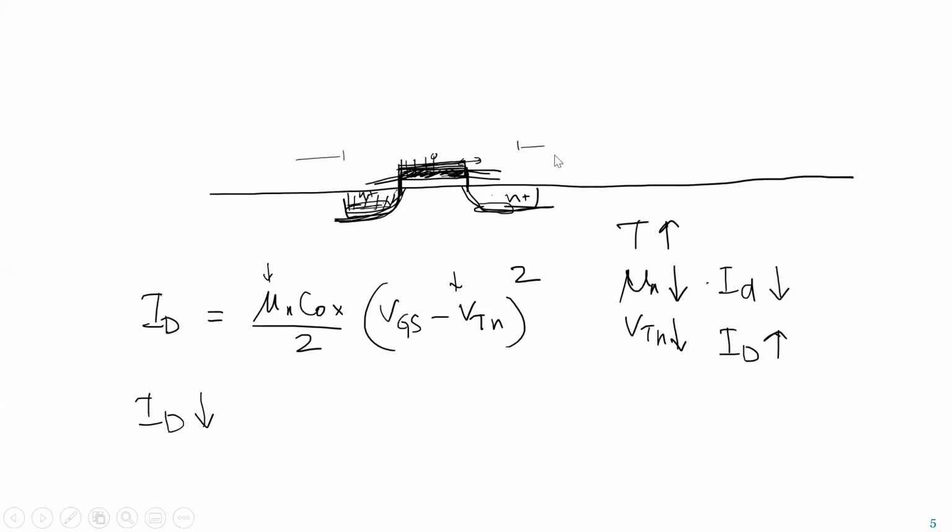That's just a process phenomenon. It's not done by design or anything. You can design it, but that's device engineering. Typically in a CMOS process, that's what you'll see. Sir, is that the reason we can't control VTN with respect to temperature? You're asking whether we can control VTN with temperature? VTN varying with temperature is just a physical phenomenon, a semiconductor phenomenon. So what's the question?